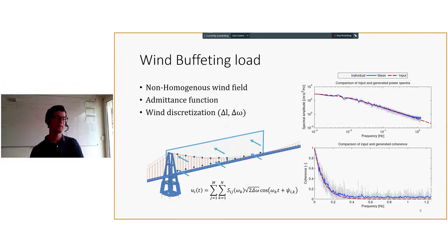We have maybe 40,000 finite element nodes, and we are able to reduce this to 1,000 wind nodes, where we actually calculate the wind field, which is then projected to a bridge. This saves a lot of time, and also our algorithm to calculate the displacements and the turbulence intensities was specially designed for this performance.